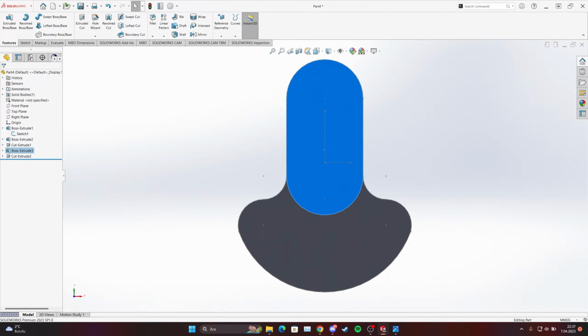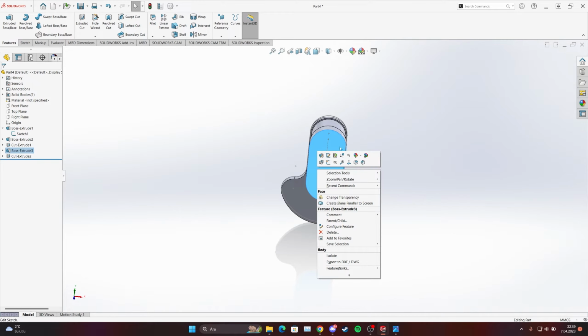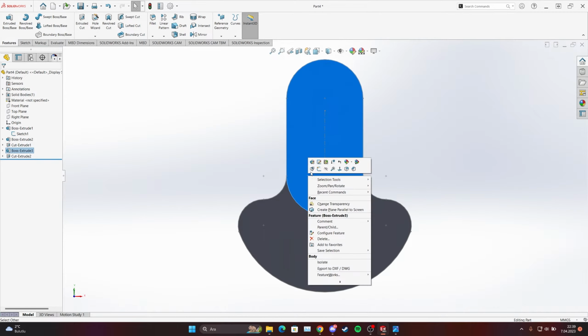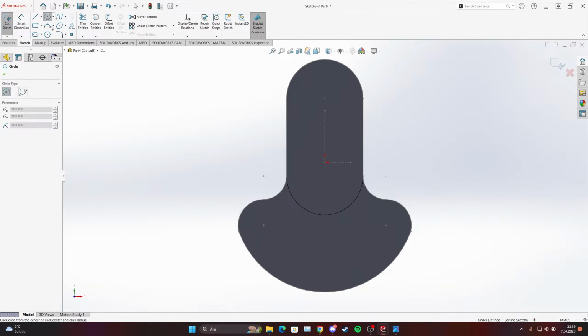And then what we will do? Okay. Right now, the next one. Make it normal from here. Start sketch and another circle. Come to here so you will see the center point of this arc. I will show you one more time. We are on the sketch. We are choosing the circle.